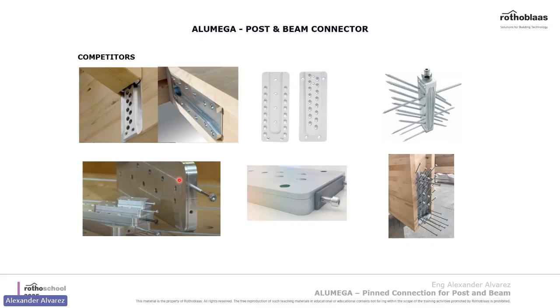However, as I said before, everything has pros and everything has cons. The locking mechanism is a good idea. However, you have to think about the tolerances as well. On a construction site, you can plan everything as much as you want on paper. You can draw the cleanest drawings ever, and then you go on site and it's off by 1 inch or 2 inches or off by a lot. Then you look at your paper and you look at the construction site and it didn't go as planned. So you want to think about tolerance as well. In case the beams are not the size you're looking for, you have to make sure you can adjust a bit.